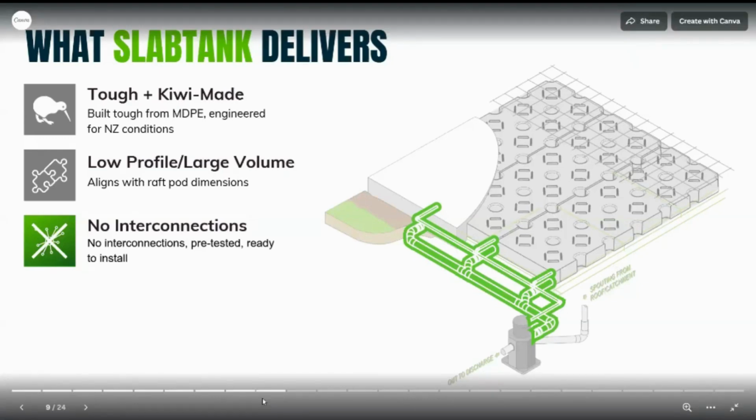Could I jump in on that one, Peter? For sure. Yeah. So I've done a bit of work on that with hydrocarbons and HDPE. This is an MDPE, which is similar except for the density. There is no adverse effects on the polymer from hydrocarbons. And in fact, one way we can demonstrate that is that the HDPE liners are commonly used as primary containment in petrol storage areas.